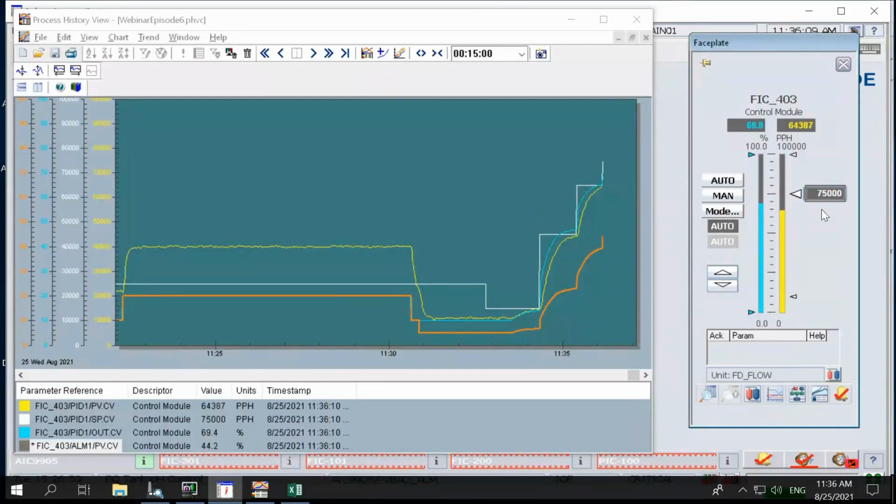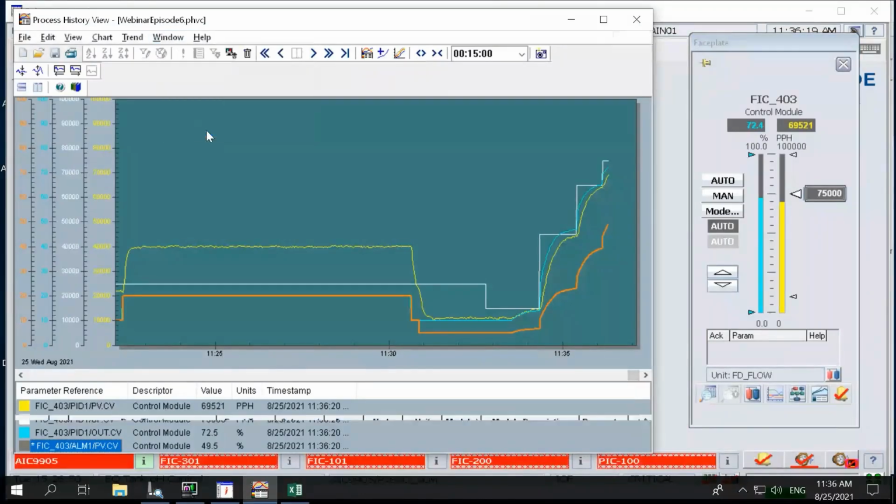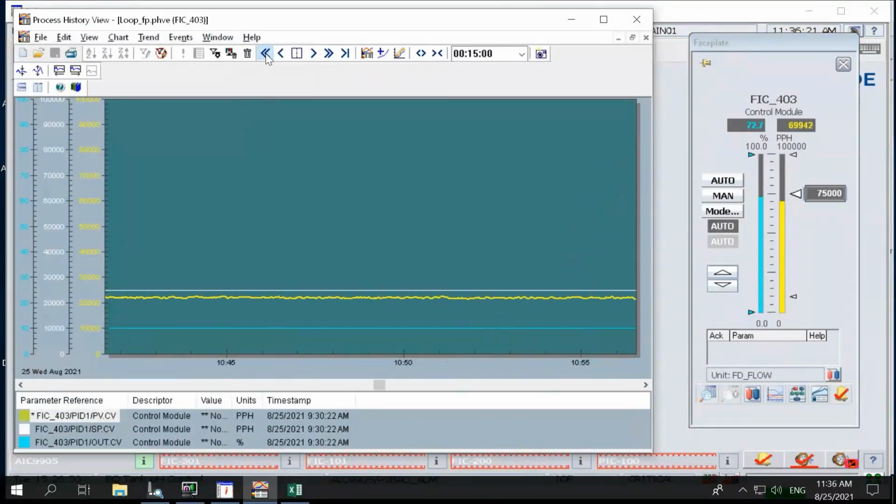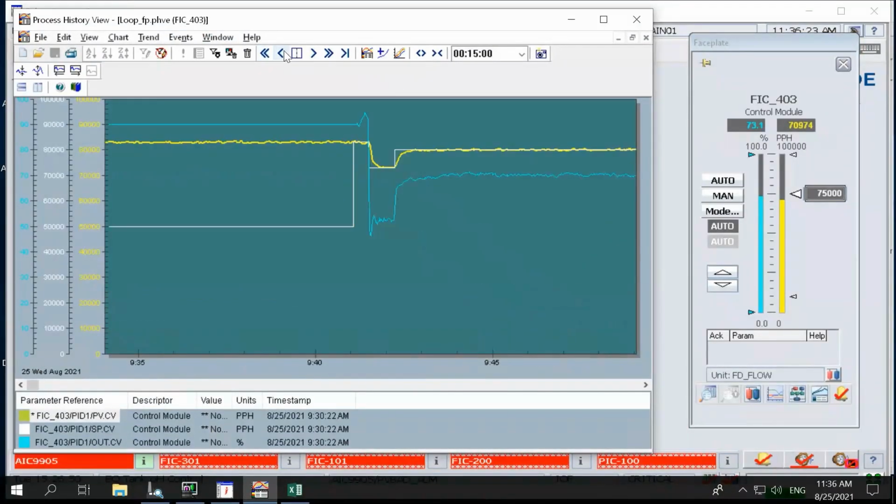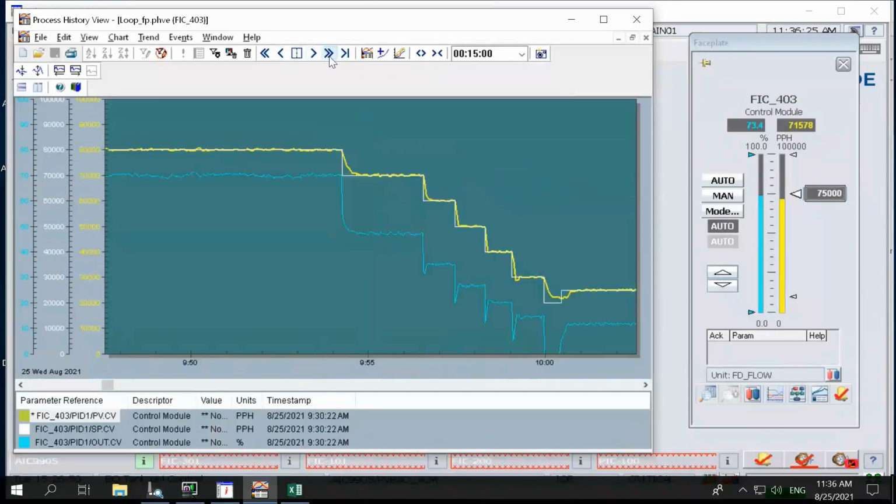And that's a bit different from what we had before, because before we could tune it at only one end. Go back to over here. Here I tuned it at the upper end and was getting less and less stable at the bottom end because the process sensitivity was increasing.